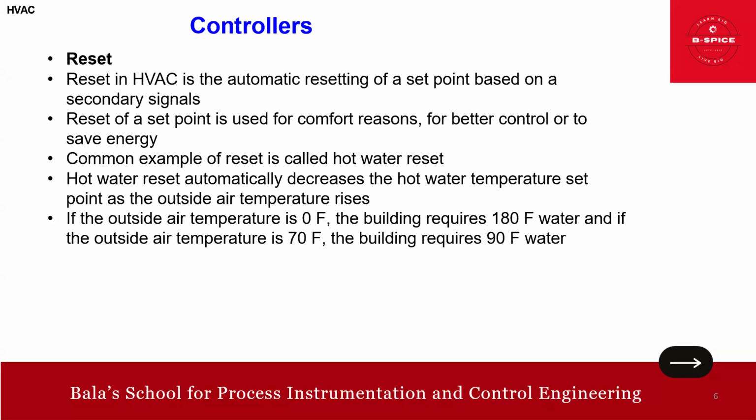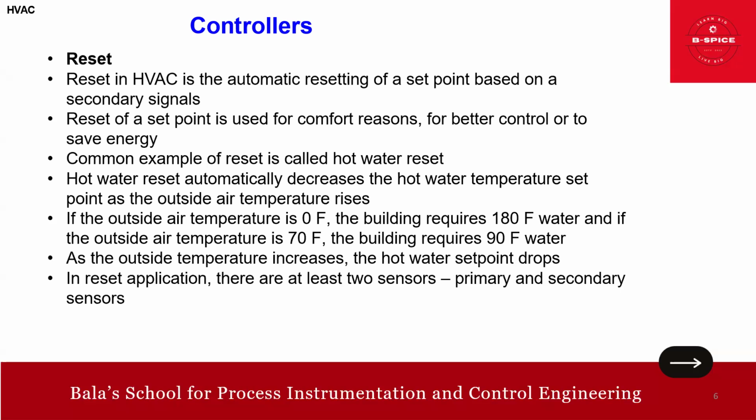So the point to consider here, friends, in a reset application, there are two sensors actually. Just remember this, primary sensor and secondary sensor. Okay. So yeah, in this example, actually, two sensors are used, right? One is outside air temperature, other is the hot water supply, right? So yeah, that is what primary and secondary.